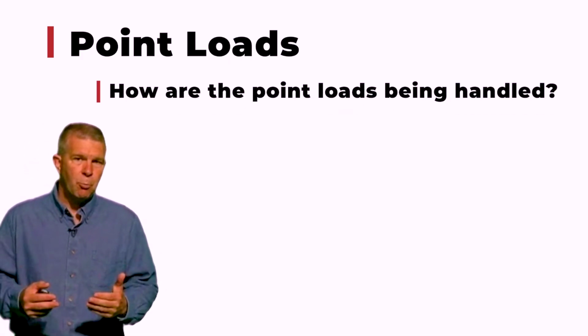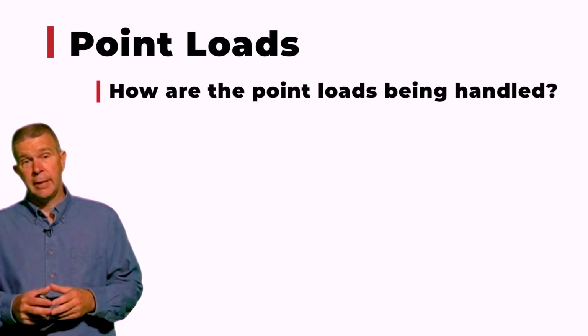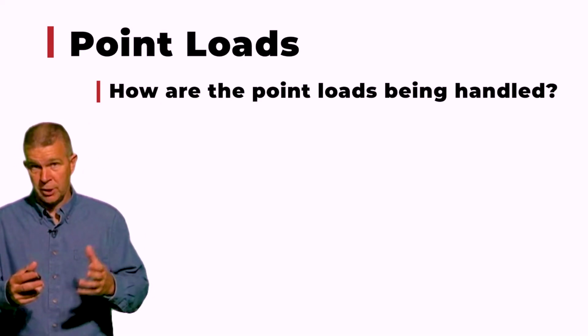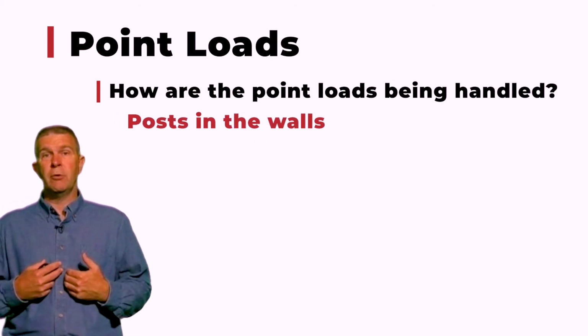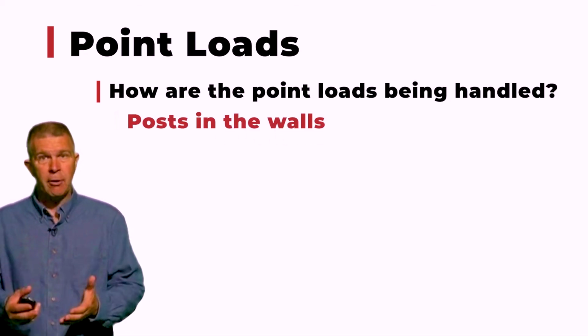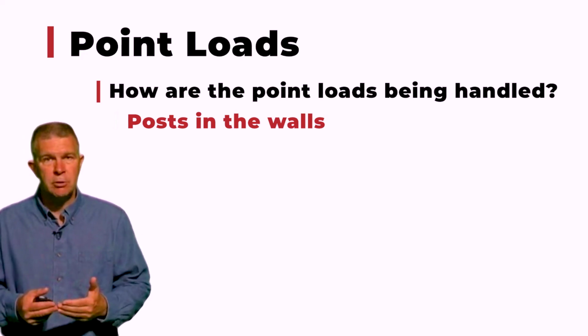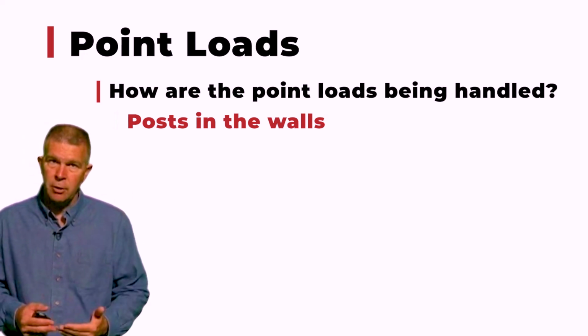So how do we handle these point loads? Well, in the not worst case scenario, but what is commonly done, is we put a post inside the panel. The designer determines what the loading is in that area of the wall panel and incorporates a post very clearly into that wall panel to carry that load down through the wall